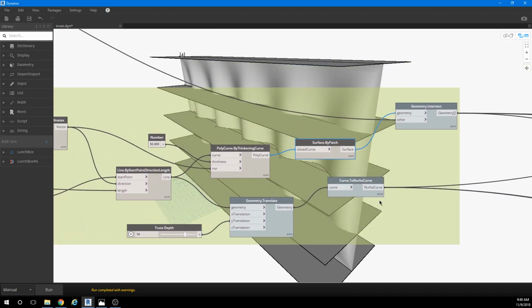These are our new intersecting surfaces that we're going to use to generate this actual curve line. This happens to be lining up with the sine wave, but you can see how these don't actually generate lines where they're intersected, and that won't happen until we get to this geometry intersect. So I'll turn the preview on for that, and now you'll see those highlight. I think I can select them to get them to turn blue. So you can see all of those lines are turning blue. They're just not showing up quite clearly down here.